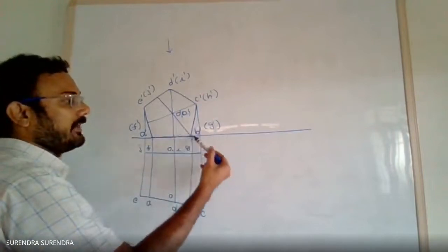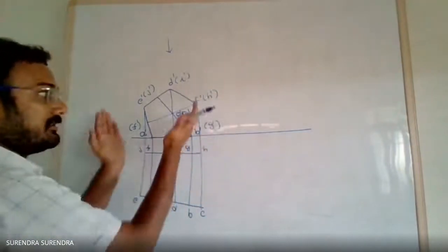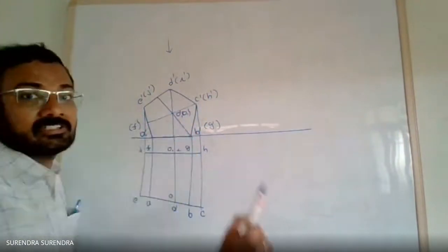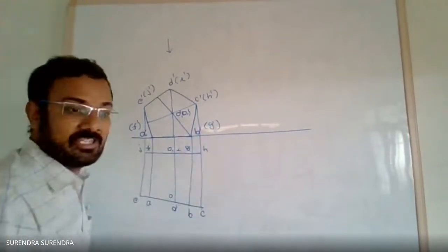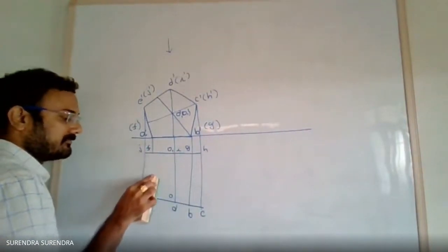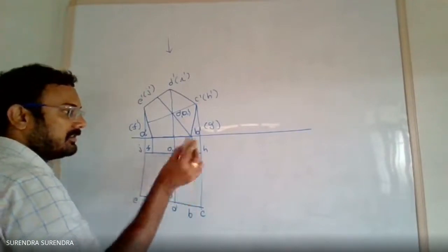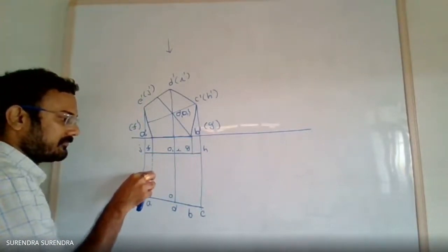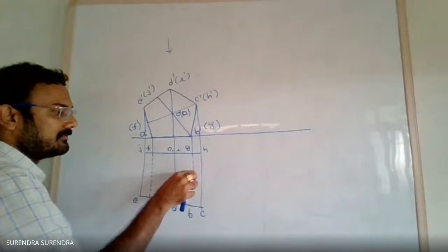But the edges BG and AF are hiding, since when you are seeing in this direction, as it is inclined in this way, these 2 points are on the other side of the viewing direction. So draw AF and BG with dashed line.